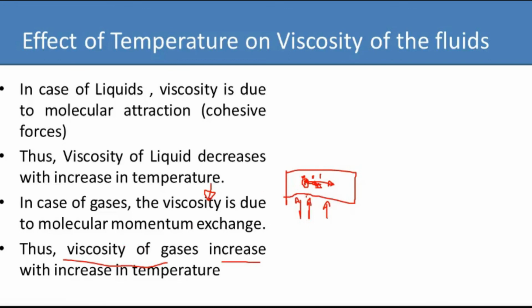Now in case of gases, as the temperature increases, molecular momentum will increase. Because of that there will be a higher number of collisions, and all the molecules will be excited. The more these molecules want to move, the more they collide with other molecules, and the more they collide, the more energy they keep transferring to each other. So because of that the viscosity of the gas will increase.